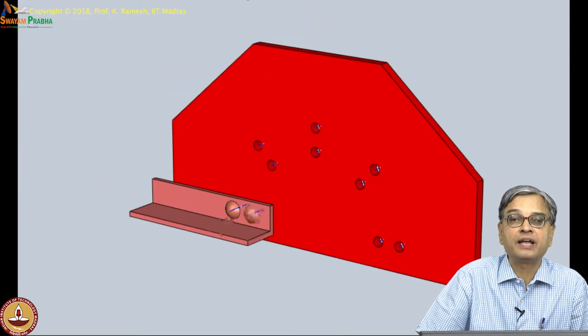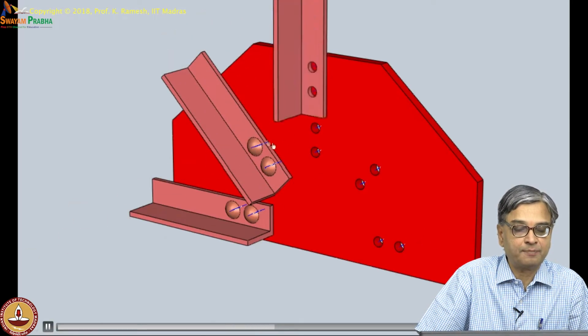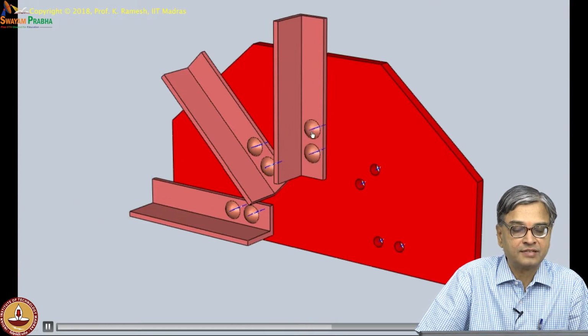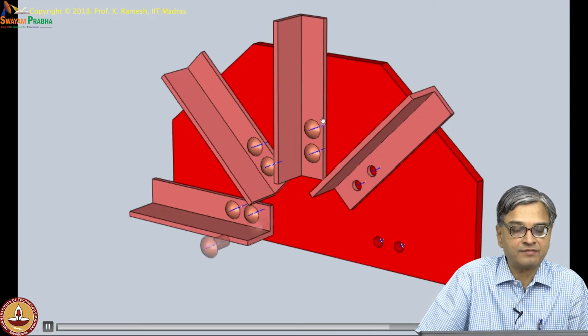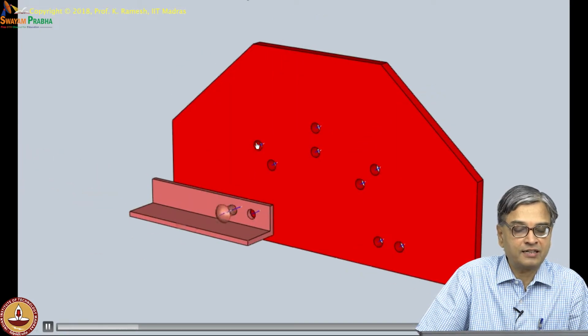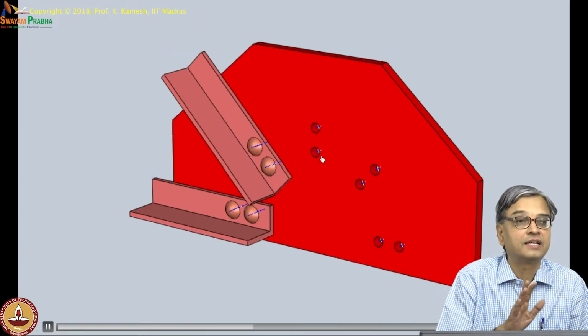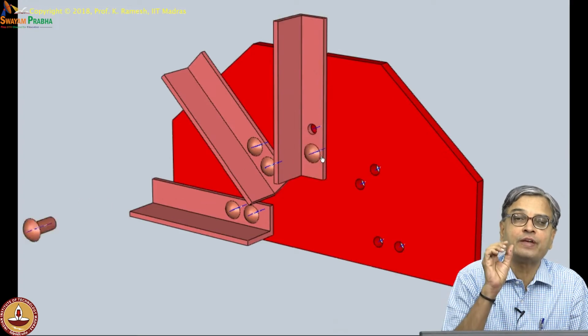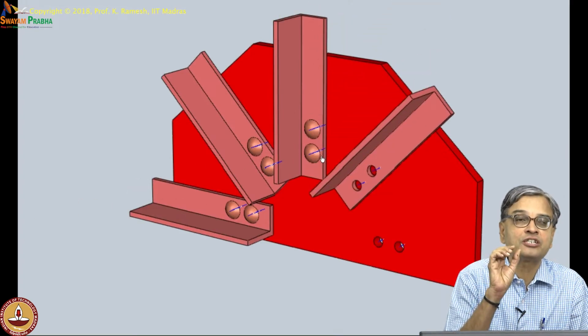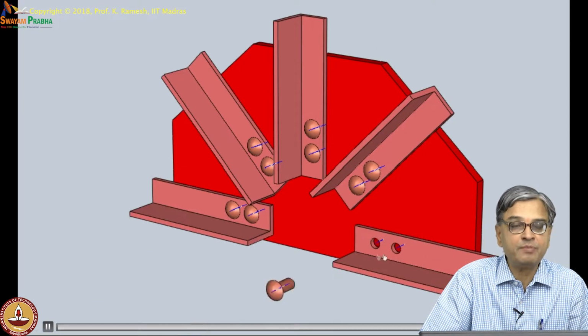it is made by riveting. And what you see here, you have the riveted pins that are inserted. They are hammered from the other side to have this head, and you must be getting used to what is workshop practice in your first semester. You might have heard that these holes are normally drilled, but drilling is not sufficient. In a riveting operation, you need to have a very fine dimensional tolerance on the holes. So, they also have to do what is known as a reaming operation.